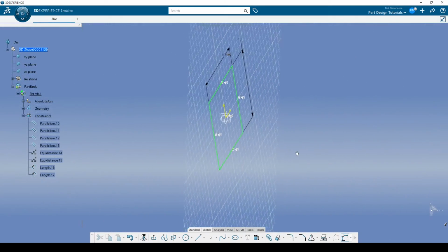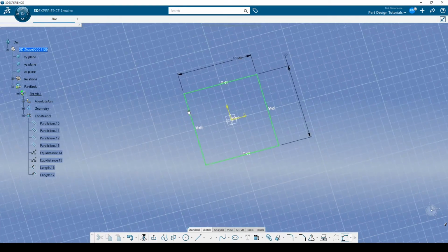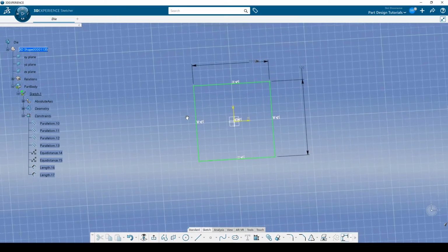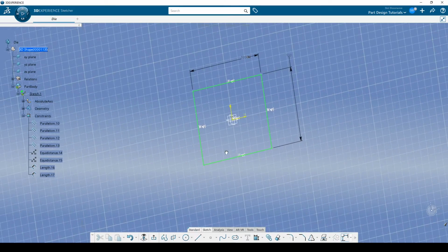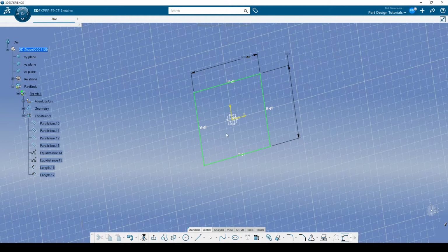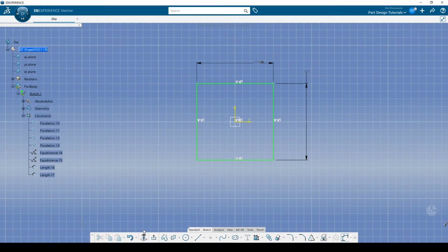Well, it's kind of good to show you this anyways, that you see we're still in 3D space. We're just on this plane floating out here. So if you do get it twisted, don't be afraid to just leave it that way and work with it as is. It's a little bit disconcerting, but it's a really good skill to learn how to do that, because quite frequently when you have more things on the screen here, it's kind of hard to see through all the stuff straight on, so you have to kind of tip it. There'll be reasons. We'll just go with that, right? But if you do want to flatten it out, you come down here to normal view, the one with the little eyeball and the plane sticking out, you hit that and it will flatten it out.